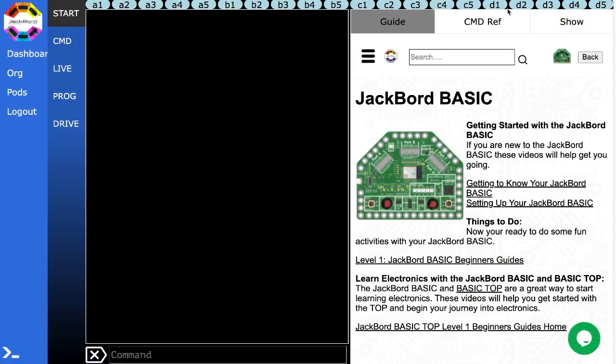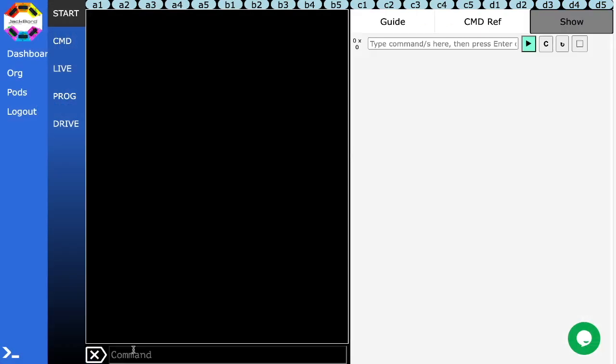So now on the dashboard, we'll just go to the show page. We'll just quickly put in the gauge command. So we go put gauge 10, 150. The value we want to show is the S_light variable. Going to make the width equal to 400. Going to make the name equal to light and lux. The minimum is going to be 0 and the maximum is going to be 64,000. So we run that.